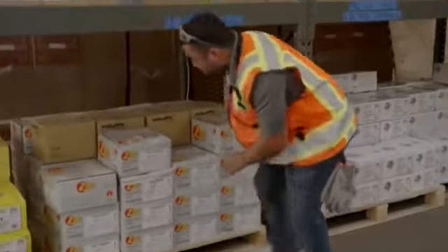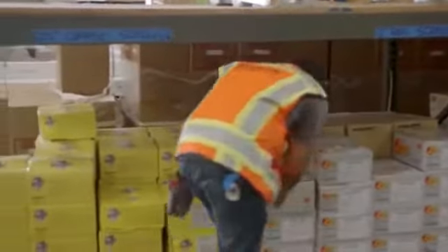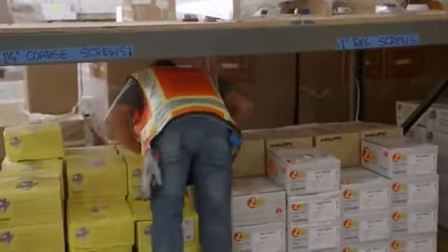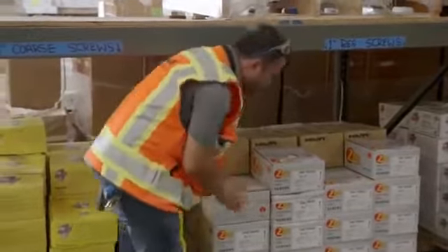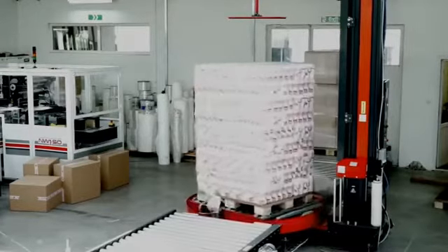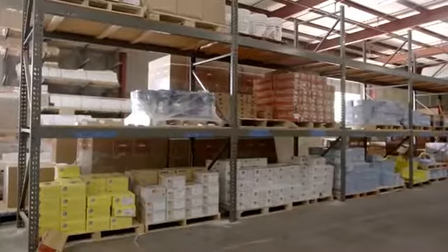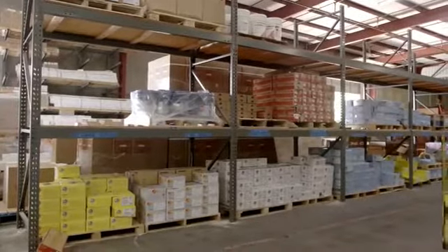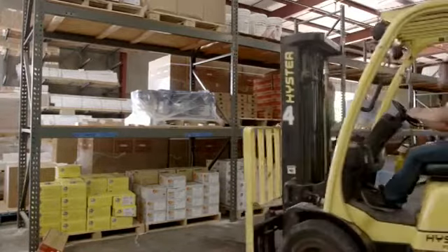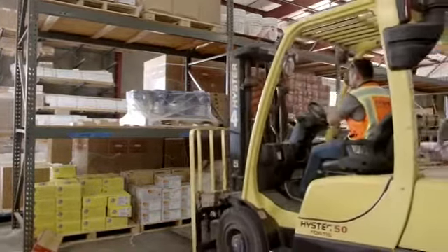Prior to picking up any load, inspect it and center it as much as possible. Secure the load so it is stable and arranged safely. Loads should be secured by wrapping or banding when necessary. Approach the load slowly and carefully, and make sure the truck is squarely in front of the load and the forks are set at the correct height.